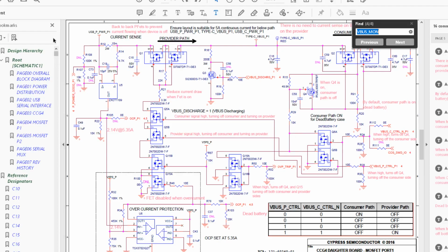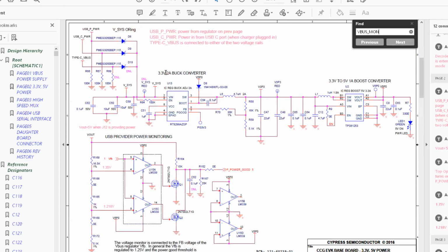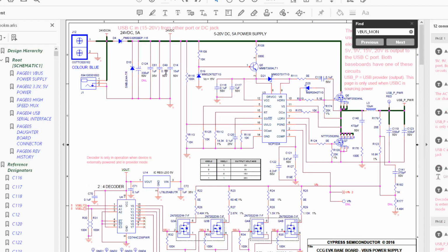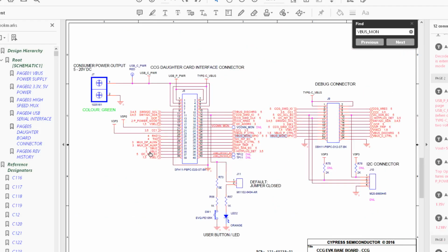So there used to be a while ago the power good connector on this pin. So it would see if your P power was regulating well, so a voltage divider going into the CCG. But they've changed that, and it's actually the same net. They reuse that net, and they put it here, power good. They've decided that it's better to look at whether the device is in regulation, that the feedback voltage is correct when you're providing power, rather than looking at the actual voltage.